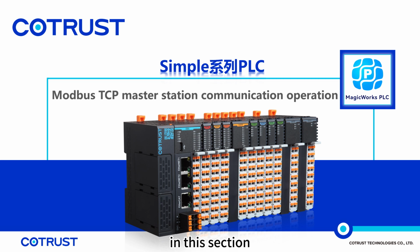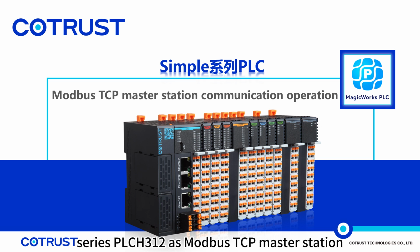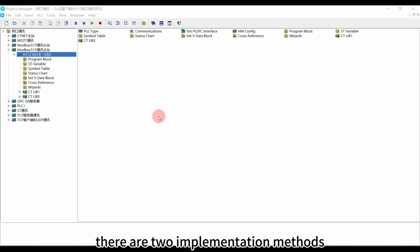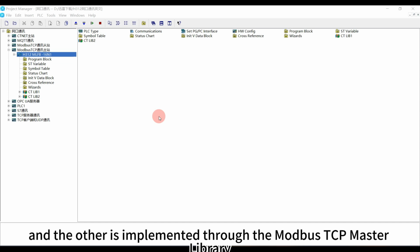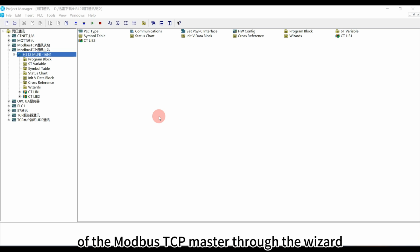In this section, we introduce the communication operation of the simple series PLC H312 as a ModbusTCP Master station. There are two implementation methods. One is implemented through the wizard, and the other is implemented through the ModbusTCP Master library. Let's first demonstrate a configuration of the ModbusTCP Master through the wizard.